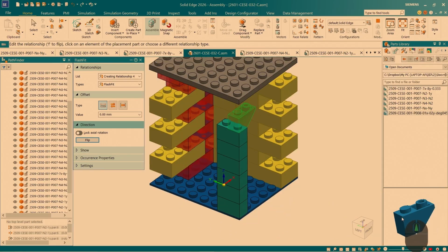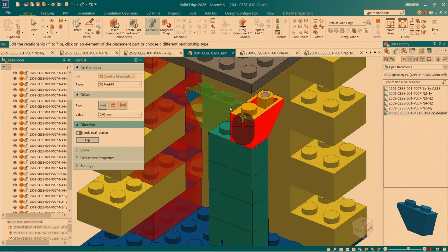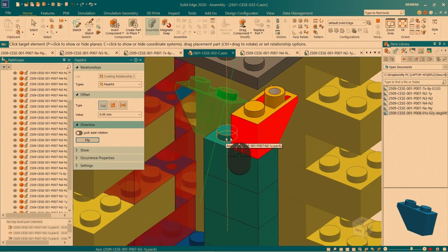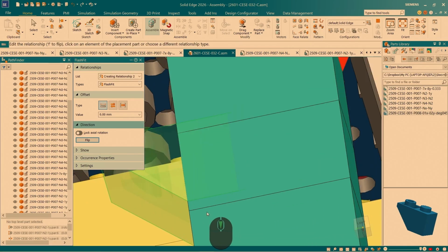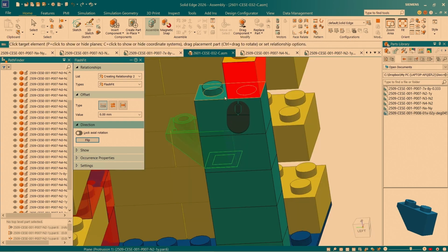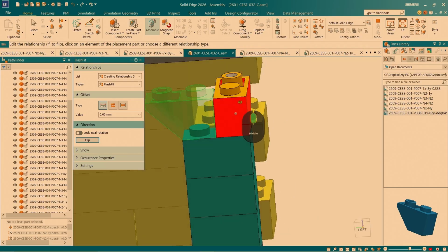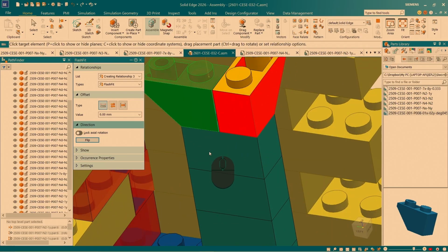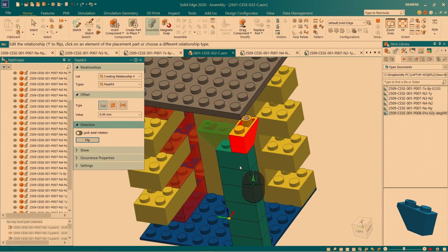All right, and I'm going to rotate the part around and drag in another copy of it here. And I'm going to choose this peg and orient it with this peg. And we want to get the bottom face of this part so we can see the preview of what will be the bottom face of the part. So I click there, and I'm going to choose the top face here. They've been brought together. And I'm going to choose this face, and they have been aligned too.